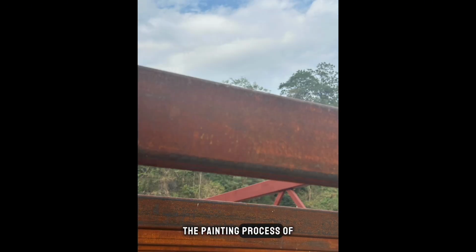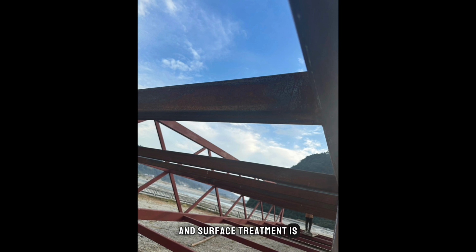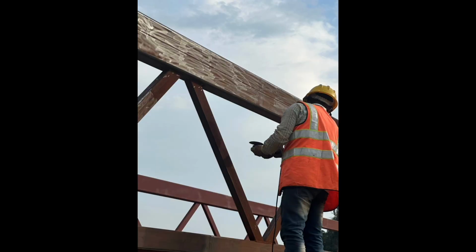The painting process of the steel members is then carried out. The members are first cleaned and surface treatment is done to remove the rust and foreign materials, after which the primer is applied to prevent the steel from corroding and also act as an adhesive to hold the paint.